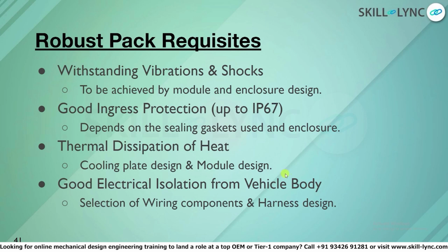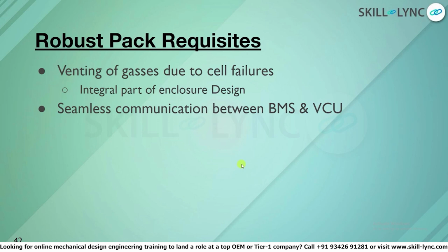And then the most important part is again the venting of gases, which is basically, in case of cell failure, you need to vent out the gases as much as possible so that the pressure doesn't build up inside the whole battery pack. And the pressure would definitely build up because these battery packs are usually IP65 or IP67 sealed, and when pressure builds up with such sealing, it is very important to vent out the gases. Therefore you need to use breathing valves, vents, for the battery pack enclosure. Whenever the pressure builds up above atmospheric pressure, these vents open up and release the gases as much as possible so that the battery pack doesn't become an explosion bomb.